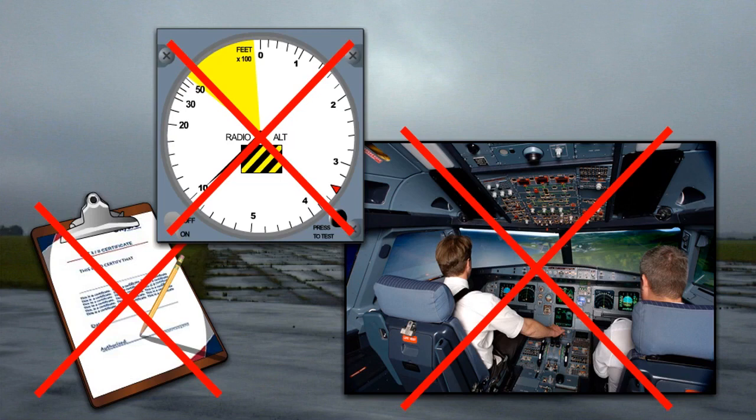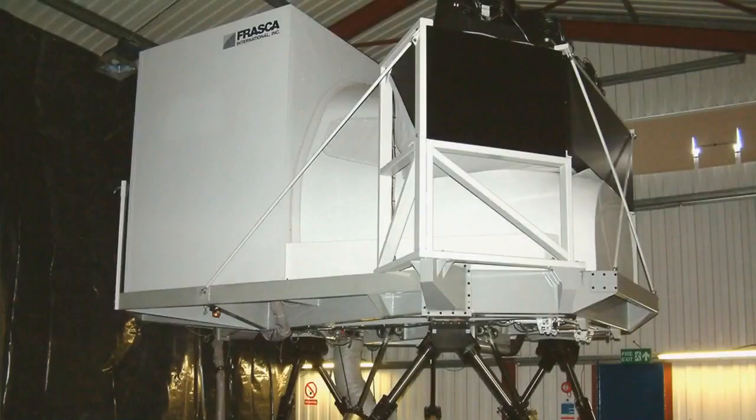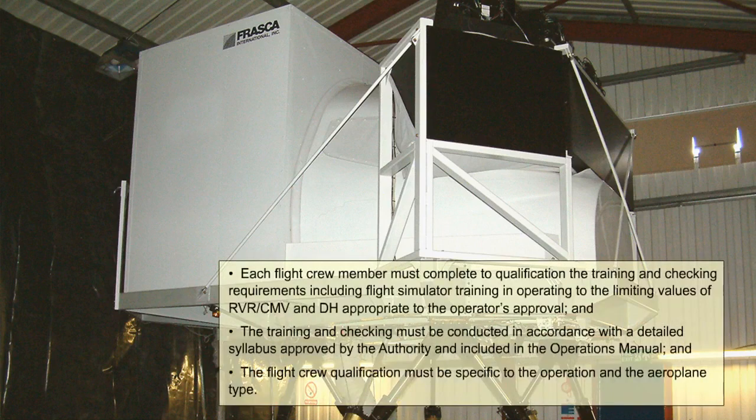Similarly, authority approval only is needed for low visibility takeoffs, LVTO. The limitations are a minimum of 150 meters RVR for Category A, B or C aeroplanes and 200 meters RVR for Category D. Additionally, the aerodrome must be approved for these operations as well as able to enforce the procedures when they are required. Finally, of course, each flight crew member must be trained and qualified to conduct these specialized operations. Here are the flight crew training and qualification requirements.